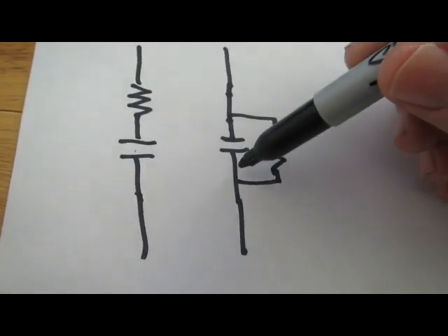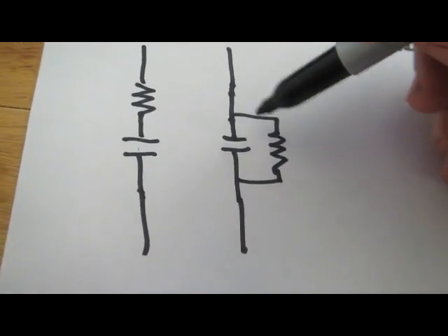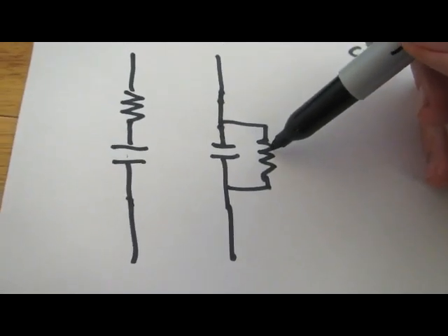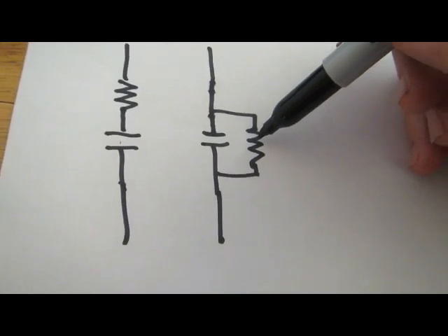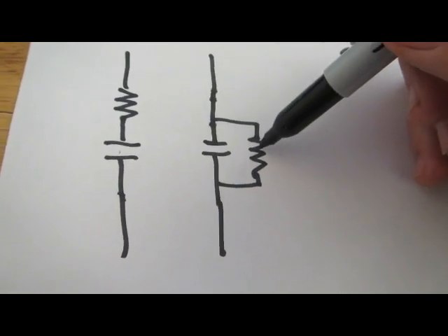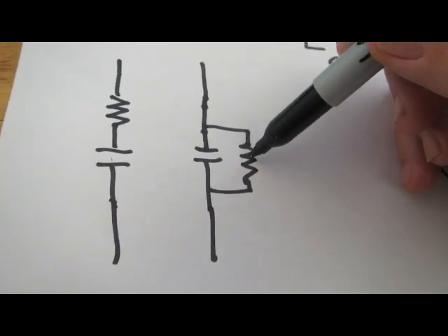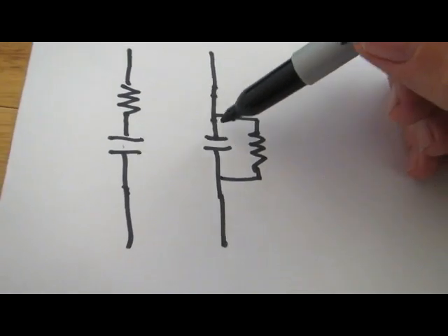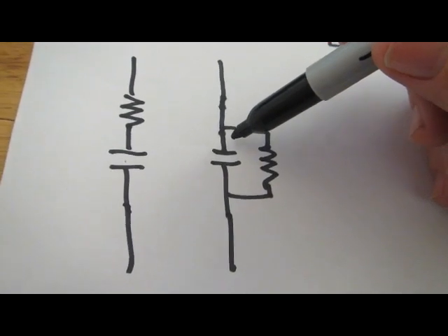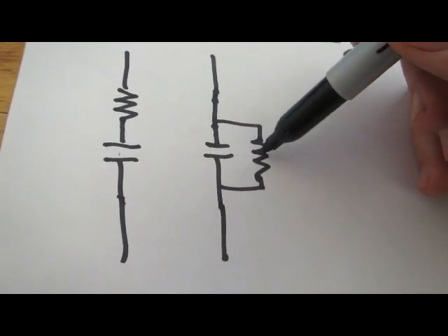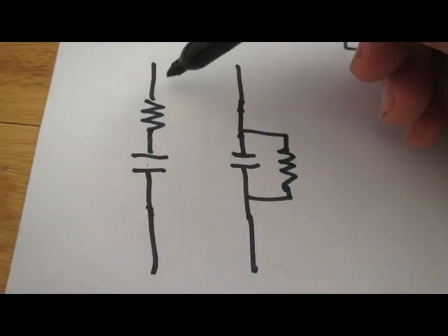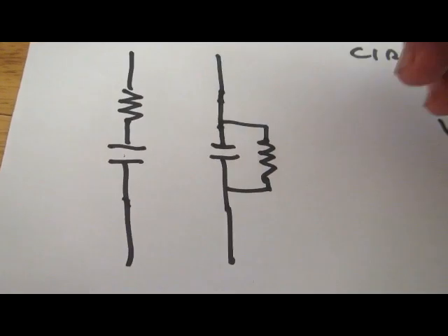Now this one, this is 1 ohm of reactance still. But to lose just that little bit of power, this is a very high resistance, and in this case it's going to be 100 times higher. So if that's 100, this is 100 times higher than that. So actually it's 10,000 ohms, a very high value. And this also, if this is in a black box, also has a quality factor of 100, a Q of 100. In this case, this resistor is 100 times greater than the reactance of the capacitor. So we can use a simple formula to relate the 2.